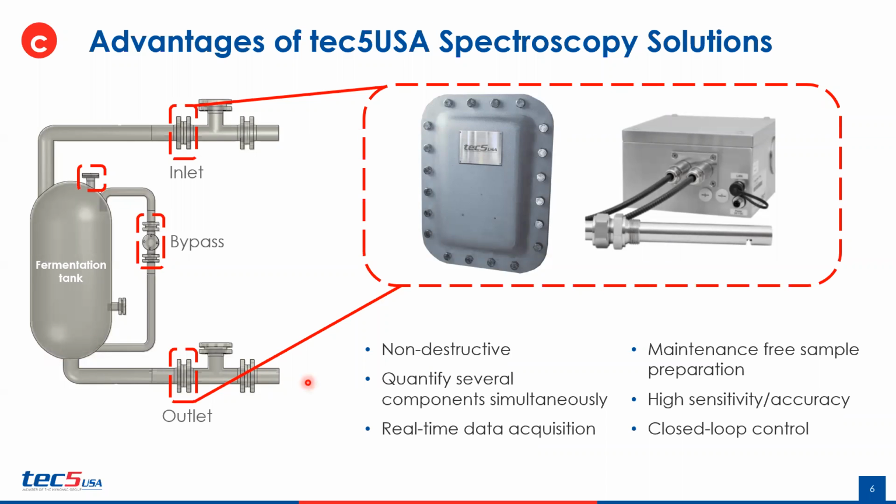And finally, if you want to look at outgoing product for quality, you can also immerse this on an outlet port. A great advantage to this is that you are not sacrificing too much sensitivity and accuracy when it comes to the measurement. Although laboratory measurements are performed with high sensitivity and accuracy, you can achieve similar sensitivity and accuracy with near IR spectroscopy in real time.